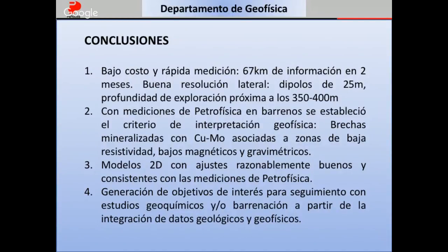Some conclusions about this survey are the low cost and fast collection of CSAMT data. We collected 60 to 67 kilometers in 2 months, and we have good lateral resolution because we use dipoles of 25 meters, and the depth of exploration is about 350 to 400.